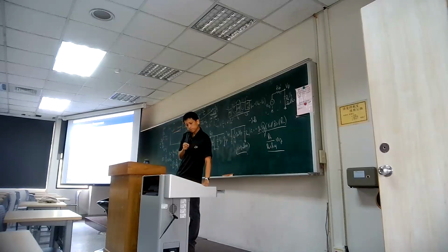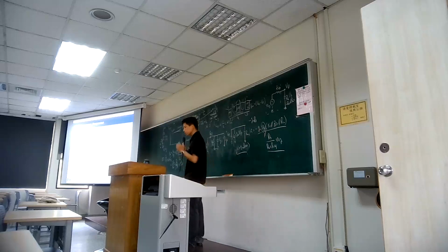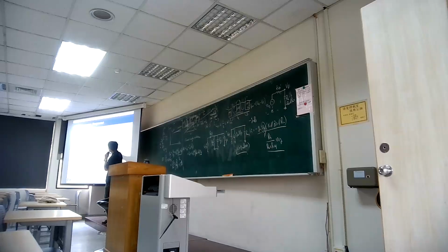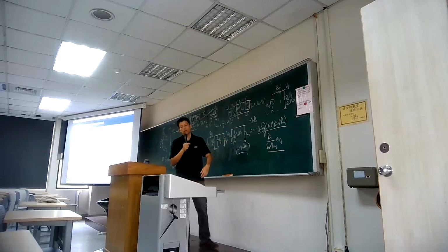So if you look ahead, I'm not sure if I showed the slide here. Maybe there's no such slide. Anyway, you can see that individually it is still the same behind the Miller effect. So you get an additional Miller factor, which is 1 plus gm RL, where RL is the output resistance.